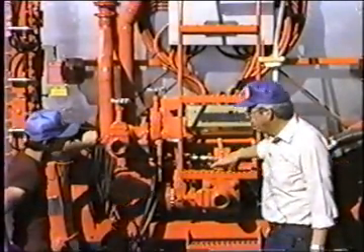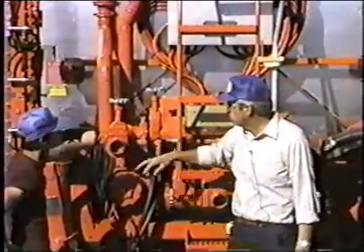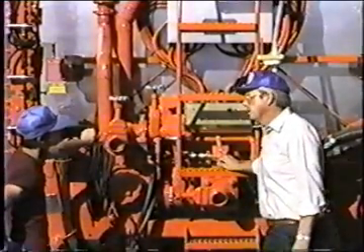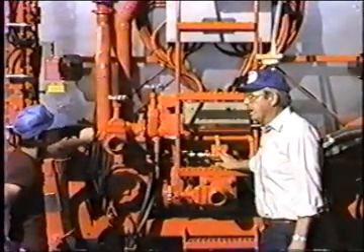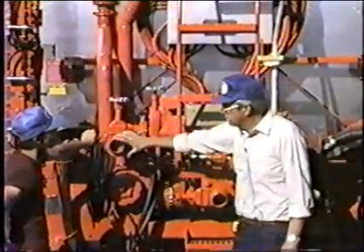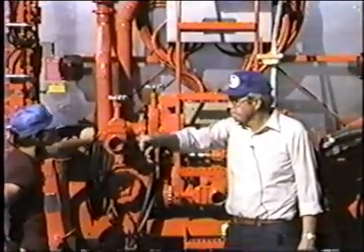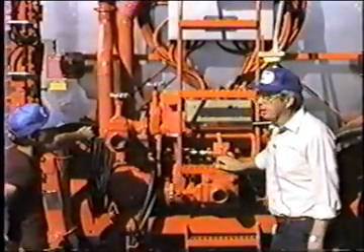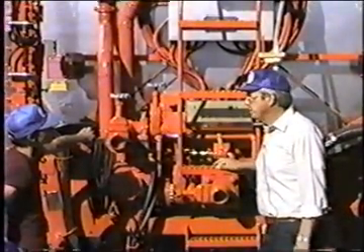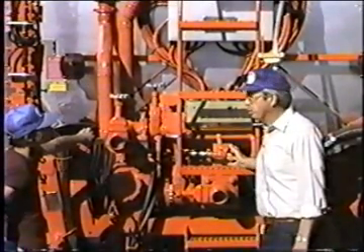Also, that's a totally unrestricted 4-inch passage that we're pushing it in here. So we're pulling it out of this transport in the top, out the bottom, pushing it in there, totally restriction-free. It loads easy and it loads fast. In fact, the only thing that is a limitation on how fast we can load it is this 3-inch hose and the 3-inch valve that we're pulling out of the tanker on. In fact, a good rule of thumb on that, 3-inch hose, 3-inch valving on the intake side of any pumping system is good for about 300 gallons a minute. 3-inch, 300 gallons a minute.